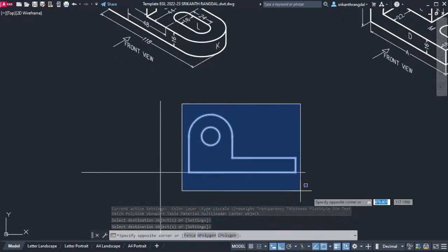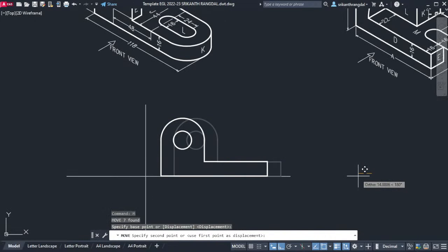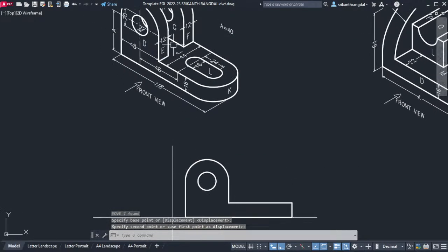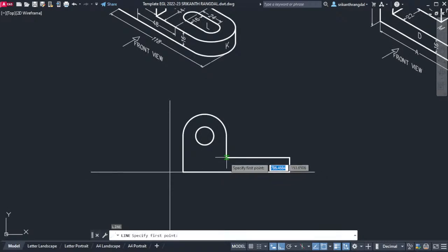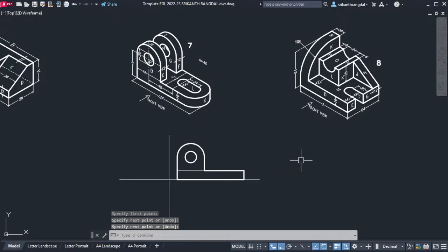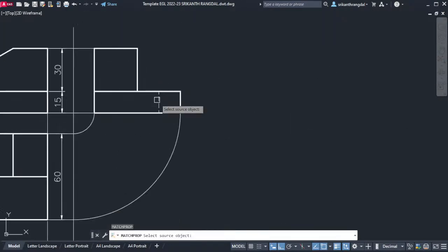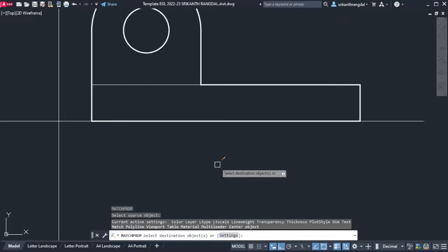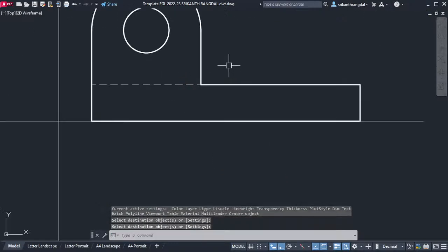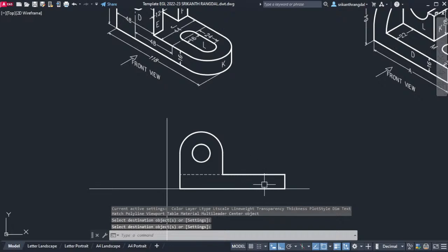This is the front view. So let me place it a little closer. Then over this edge, that's going to be hidden, so we'll have to draw this edge over from here to here. That's hidden, so hidden properties I have to take. Edge properties, hidden, and there will be two more hidden edges over here.